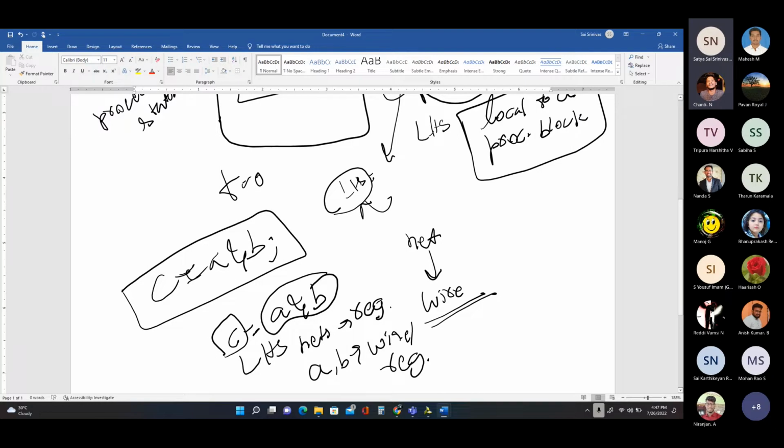Reg, don't misinterpret it as a register, because the tool sometimes may realize it in the form of a register if you provide a clock signal. If you don't provide a clock signal, it is treated as a reg type, but it is not actually a register. Reg has no hardware significance. Reg and register are different. Reg is a data type. That's it.